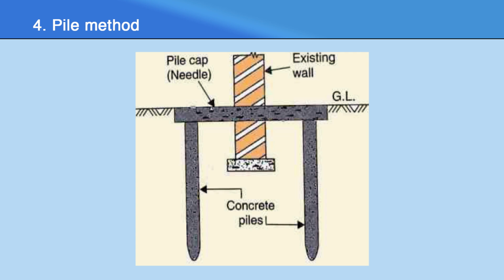This is the pile method of underpinning, in that precast concrete piles are inserted and above that a pile cap or a pile beam is used, which will serve as a pile cap in future. So, this is the pile method we generally use for clay soil.